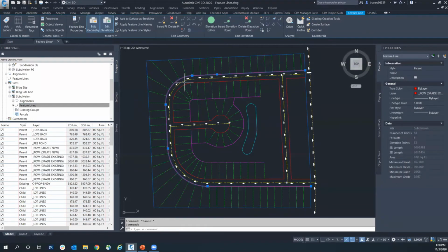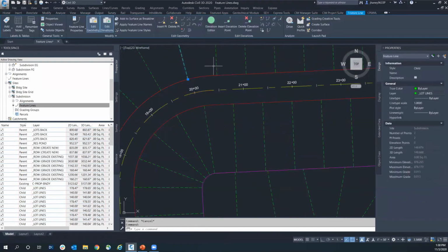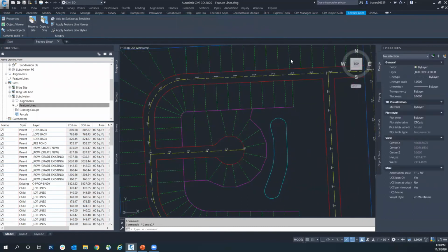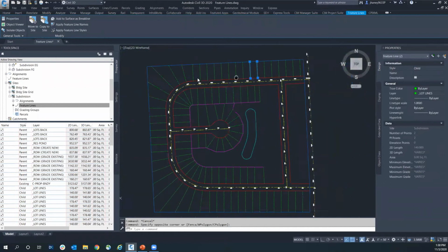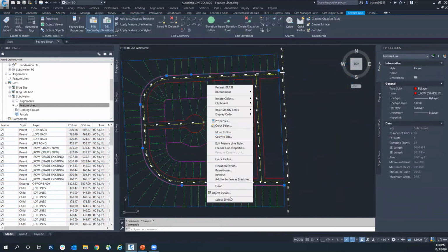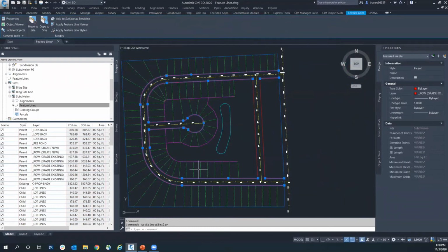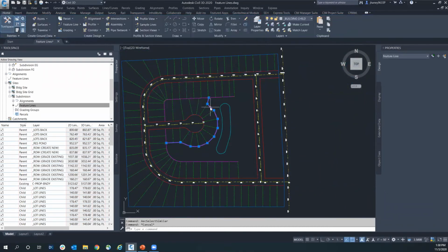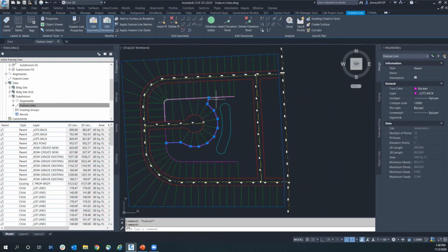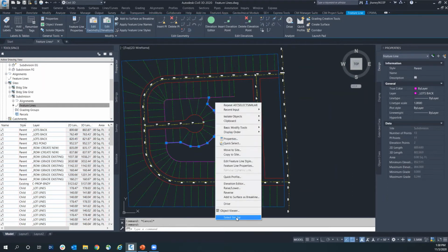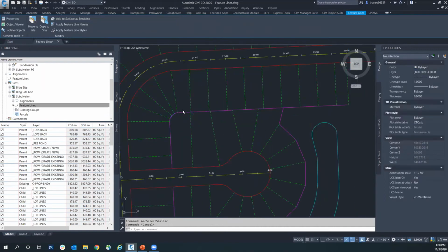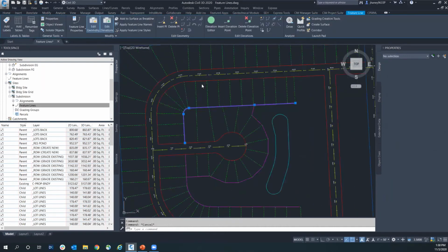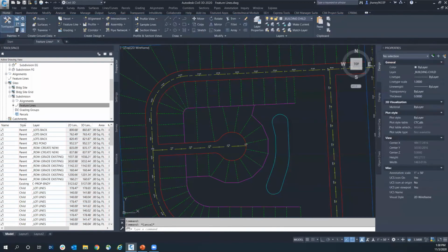So these elevations are going to dictate my lot line points, because my lot lines are set up as a child style. These back of lots that I'm going to select are also a parent. So if I change anything here or here, these elevations are going to change.